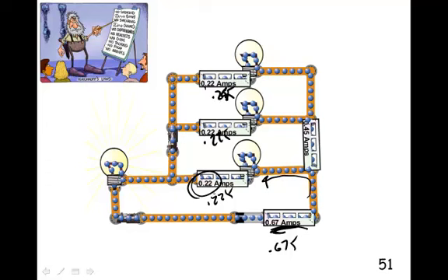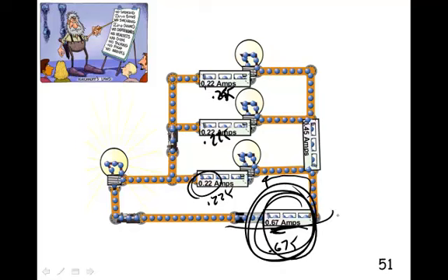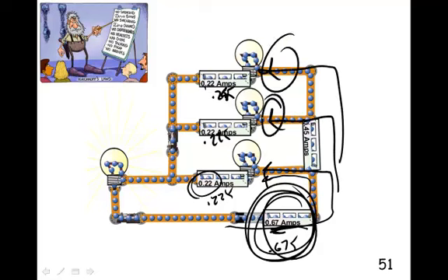And if you add up 3 times 0.225, you end up with 0.675. So the current that comes out of the battery has to branch into these 3 elements that are in parallel. So the sum of all these 3 currents is equal to the total current that I had. It's neat. That's Kirchhoff's node rule for current.